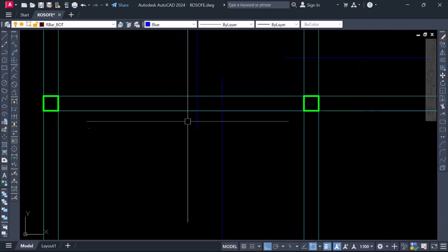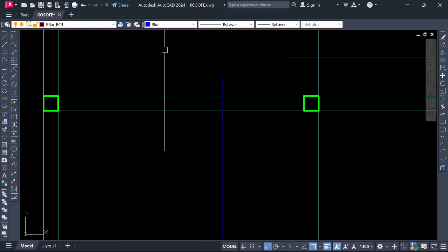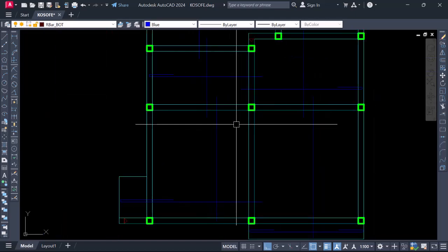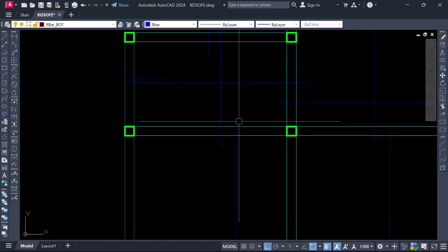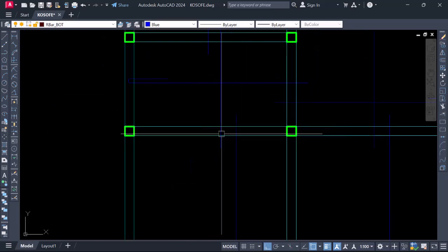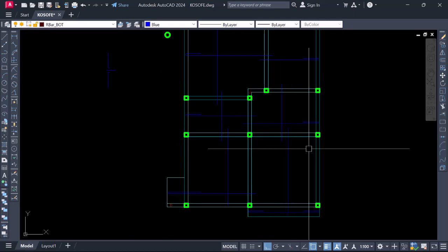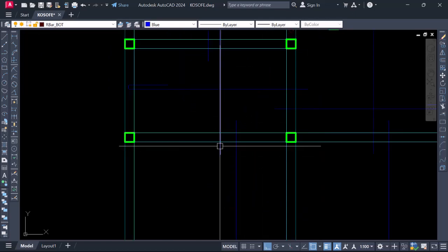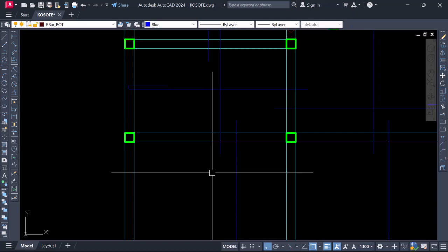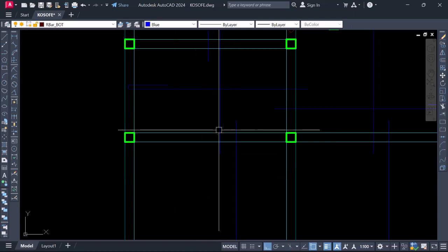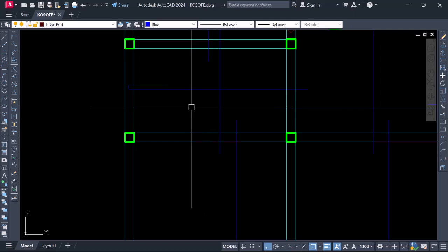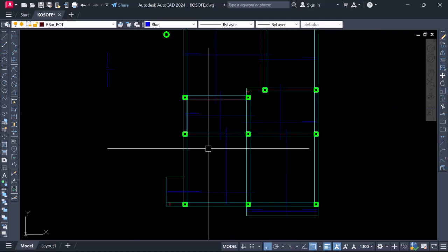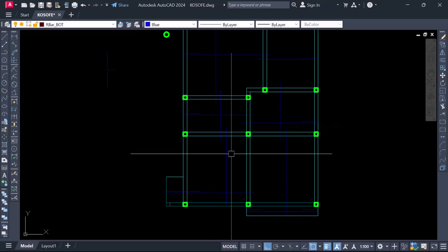So in doing this, this has already taken care of the lap length. Mind you, we are going to use Y12 in this simple detailing. We'll be showing you when we'll be calling out this reinforcement. We are using Y12, and you know the lapping length for Y12. For the compression zone we always have 50D, and for tension we have 40D, but in this we're going to be using 50D across all reinforcement.